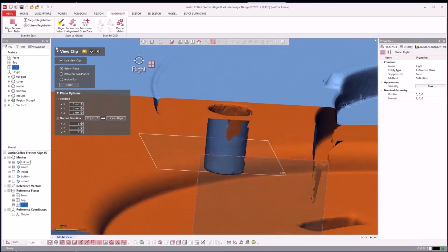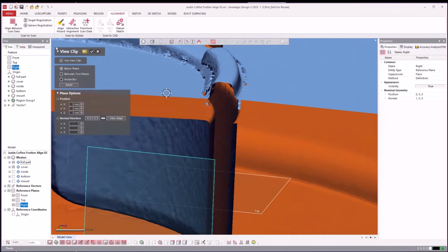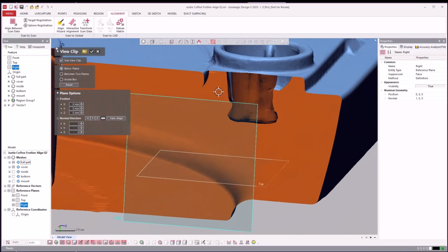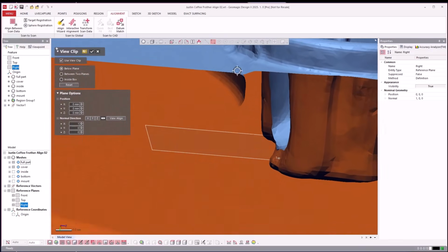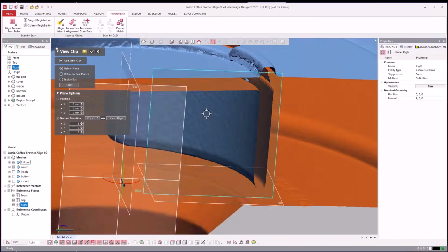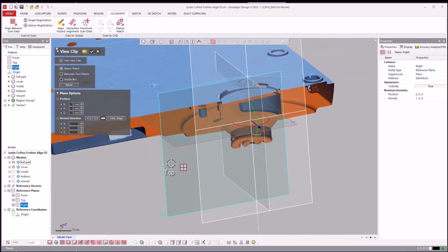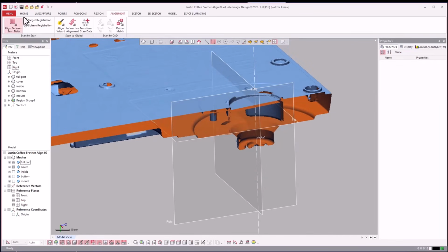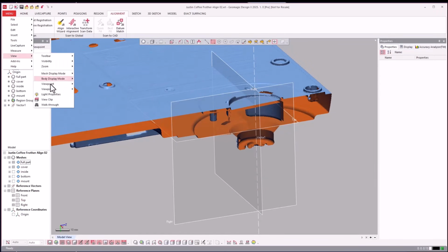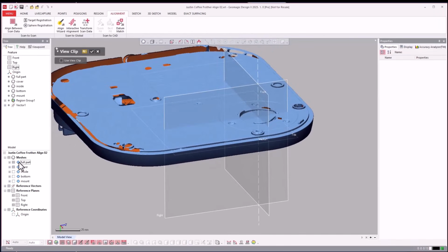And if you want to see how accurate that is, look at that. So one is the scan there, dipping down. So very, very accurate there. That piece is locked in. And then don't forget to turn that off so your view clip here stays on. So we align the first one. Hit OK, get out of the view clip.